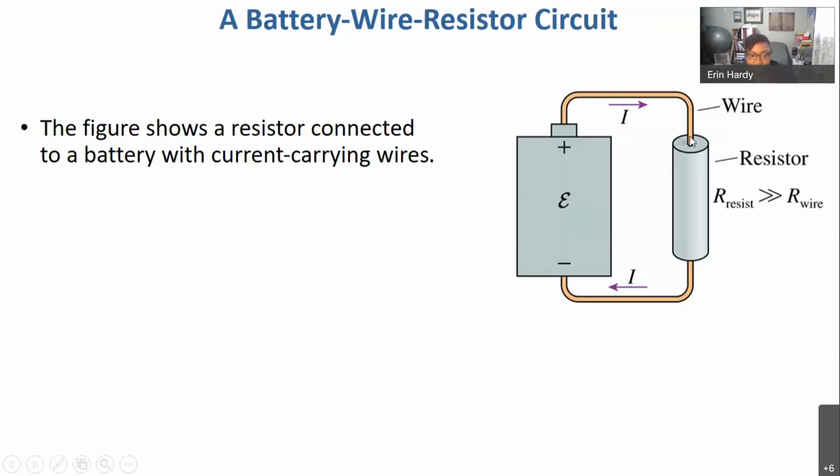So it might be like 1.48 volts or something, where the remaining 200ths are something that we could attribute to the wire segments themselves. So there's no way to actually idealize the wire so that there's no resistance whatsoever. But our goal is for the delta V across the wire to be really small compared to the delta V across the terminals of the resistor, and thus the delta V across the terminals of the battery.